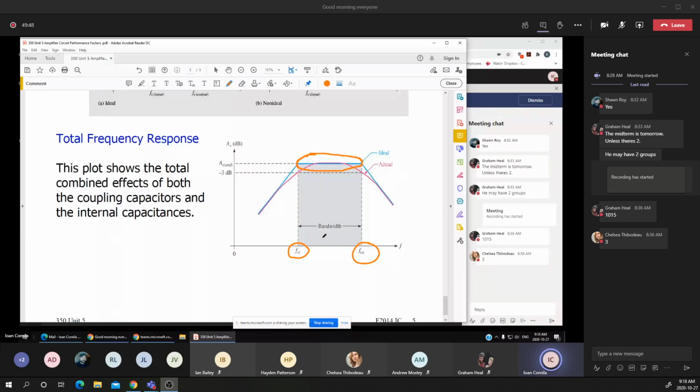And for these frequencies, again, we have to make sure that we are using signals in this bandwidth. Usually we are designing and making sure that the bandwidth of a stage, of a transistor, of an amplifier, is a bit larger than required by the theoretical values, just to make sure that we have a good, stable, or constant gain as the frequency is increased or decreased between the two limits, the lower critical value and the upper critical value.